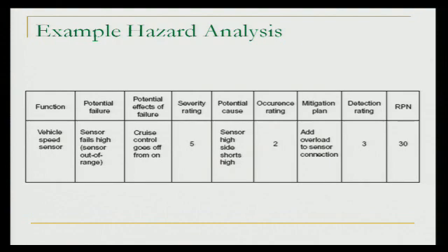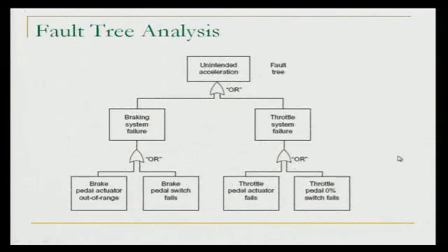Okay. Now, how do you come up with the severity rating? Some of this is by discussion over what damage would be the largest if the particular failure occurred. And so that's somewhat subjective. The whole risk priority number is somewhat subjective, but as long as you're consistent in how you apply it, it's still a useful indicator.